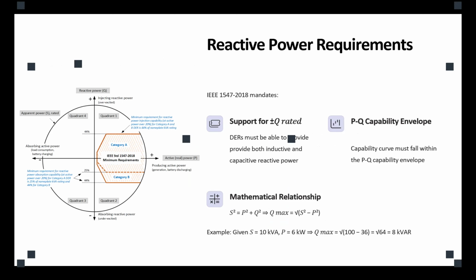The IEEE standard not only has the definition for how long you have to tolerate certain deviations in the voltage, but also provides a requirement for reactive power. Why do we have to have that? Because we don't have an infinite amount of energy in our resources. If the system could consume or inject whatever amount of reactive power the fault demands, we would be good.